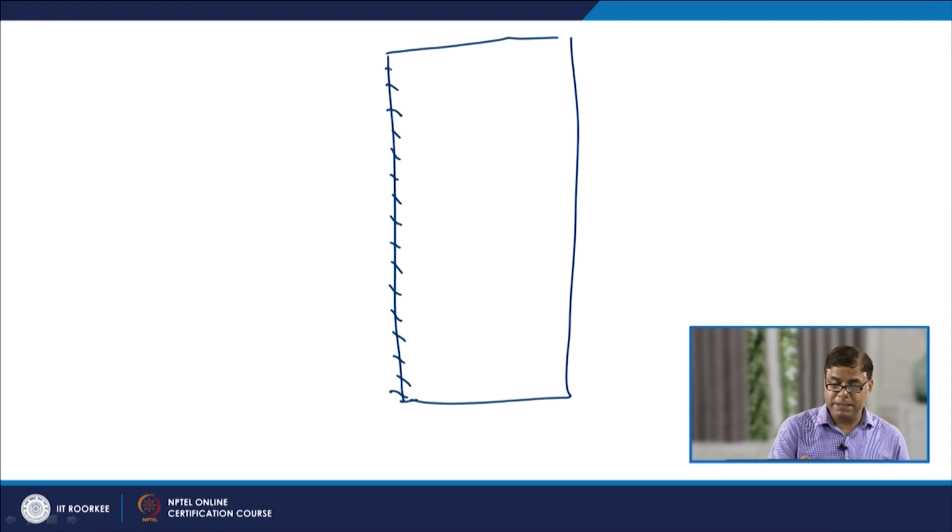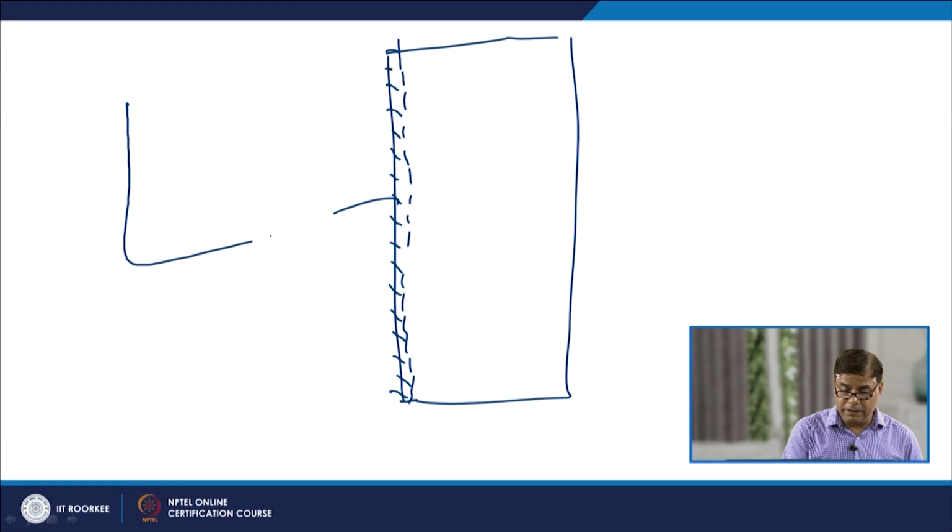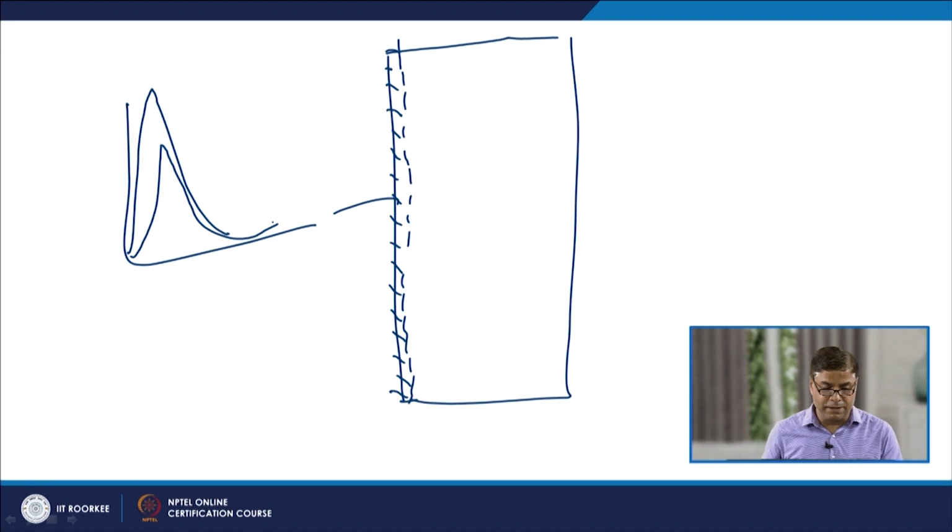So, the thermal cycle to which the base metal is exposed is similar to that of welding, and that is why the cut edge will experience a weld-like thermal cycle, and the distance slightly away from the cut edge will experience lower heating rates, lower cooling rates, and lower peak temperatures.